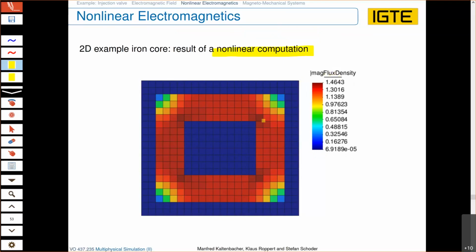And now you see, you clearly still have some discrepancy. It's not exactly at the corner the same value, but that you will also have in reality if you do measurements. But in this region, this region, this region, this region, we quite have a homogeneous magnetic field, as we know then also from measurements. And this is clearly a question of your excitation, how large the current is within the coils. Anyway, for most of our devices, it will be a must to take the magnetic nonlinearity, this material nonlinearity, into account.